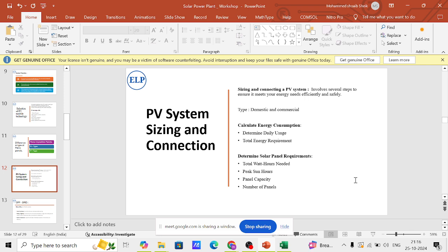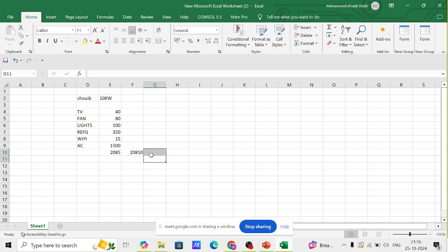So you have to inform that there will be a time when the sun is perpendicular to the solar panel, where it can produce more energy compared to the other hours. There will be production at other times, but it will not be considered in the design. So my panel can produce, as I said, take 5 hours. Okay, we go back to this now: 20 kilowatt divided by 5 hours.